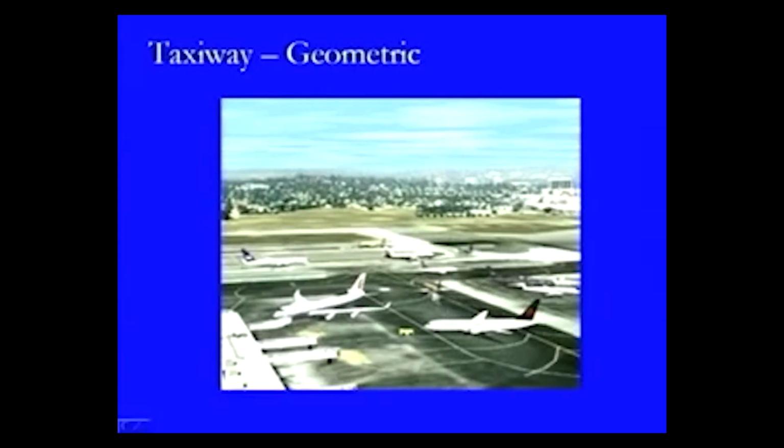This is another connectivity provided between these taxiways and this one, and this is what is termed the taxi lane. This is a terminal taxi lane because it is provided very near to the terminal and provides connectivity to the normal taxiway, and here the aircraft can go in this direction and in the other direction. We can see that there are some aircraft shown at this location standing with their nose in this direction, whereas in this direction these are standing with the nose towards the left-hand direction. So, that is how they are oriented towards different directions.